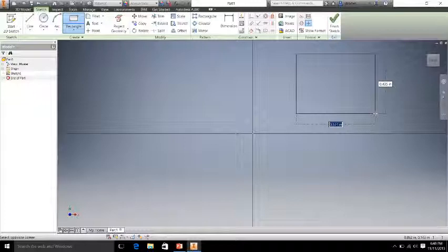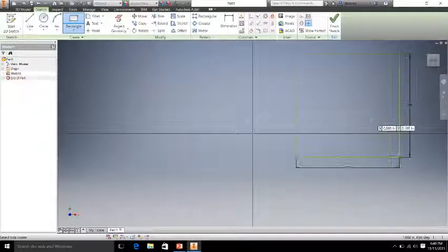So while that's still lit blue, without clicking again, if we drag it down a little bit, we can hit 0.75, and then if you hit tab, it's going to adjust to our other plane, and we can change our Y plane to 0.75 as well, because it's a perfect cube. Now if you hit enter after that, it's going to readjust our box so we're 0.75, 0.75. We're 3/4 of an inch squared.